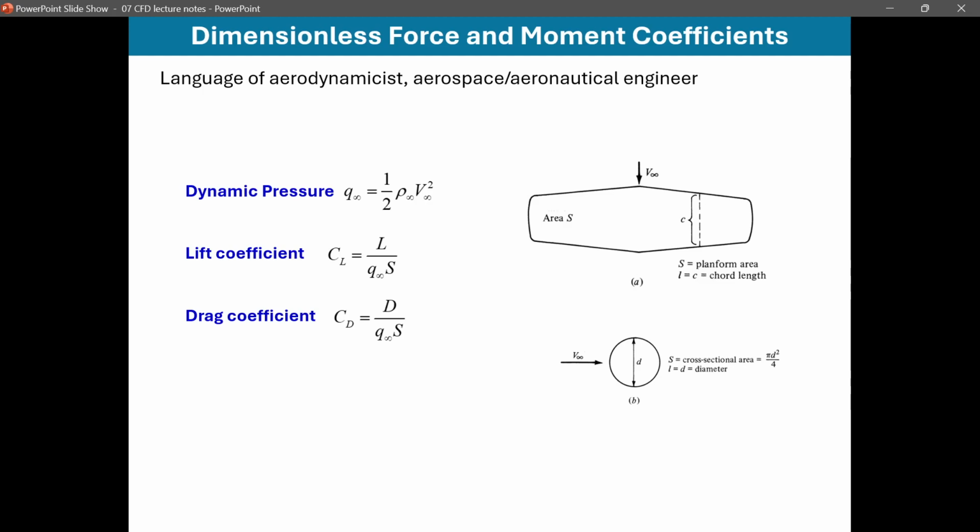Okay. How do we calculate these non-dimensional parameters for lift and drag? These non-dimensional parameters are called lift coefficient and drag coefficient. Lift coefficient, C_L, is equal to lift divided by a parameter called dynamic pressure, which is the kinetic energy of your air, or liquid, or whatever fluid in general. And it's calculated by multiplying 1/2 by density by the square of flight velocity, the moving velocity.